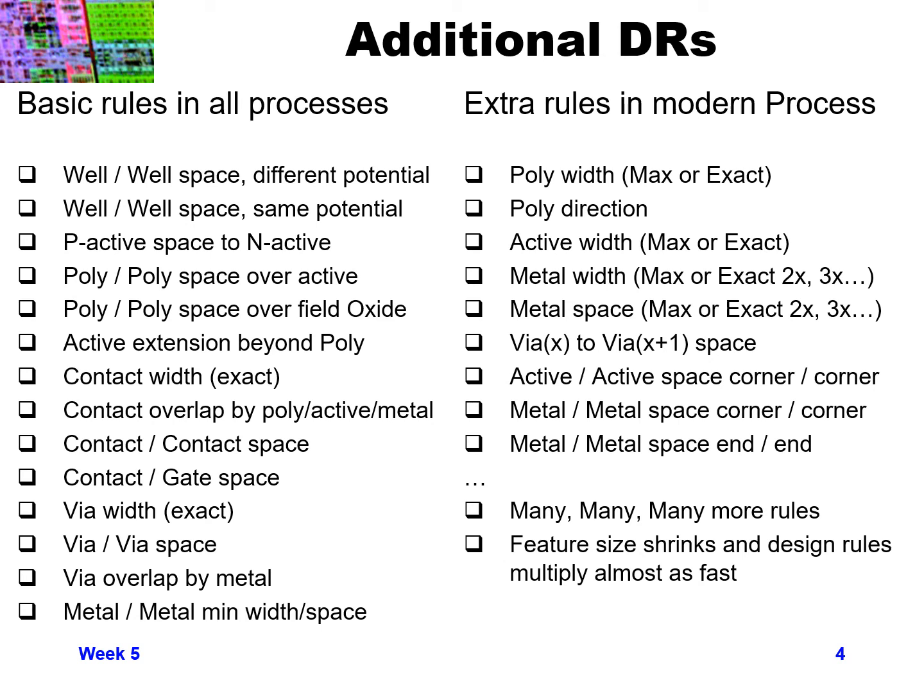Your via widths: contact is usually referring to the metal contact to the silicon. Vias is usually talking about metal to metal. So when you're going from one metal layer to the next metal layer, those are called vias, whereas metal to silicon is called contacts.